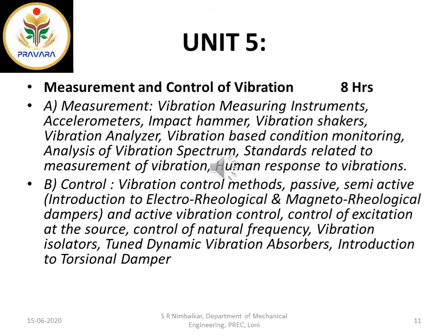Besides the impact hammer, there is a vibration shaker, the electrodynamic shaker, which is exciting the system, or we can say externally giving vibrations to the system, and we are observing its endurance: how durable the system is against this vibration. So there are vibration shakers.